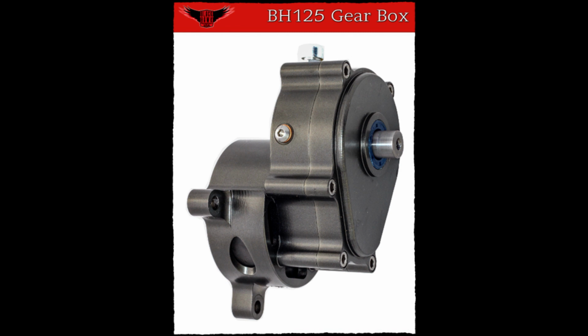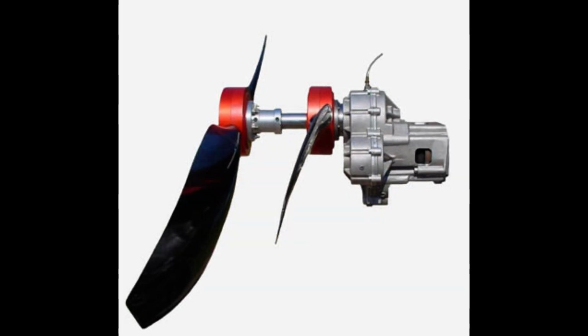A 2-cycle engine gearbox is kept lubricated with its own built-in reservoir of heavy gearbox oil. The reservoir is actually part of the gearbox case itself. The gearbox oil has to be changed periodically since the meshing of the gears will cause them to wear and will deposit steel filings into the oil. If the oil is not changed, the abrasive filings cause even more wear.